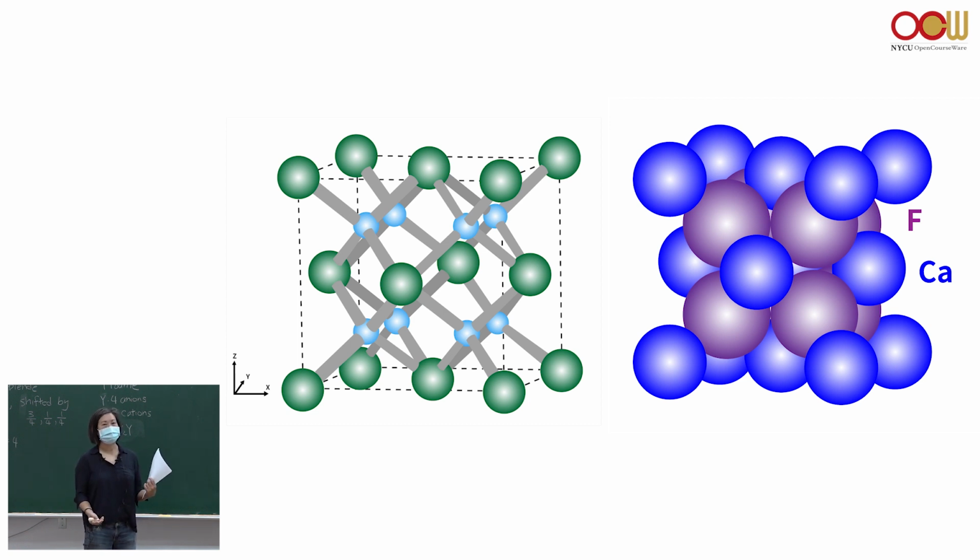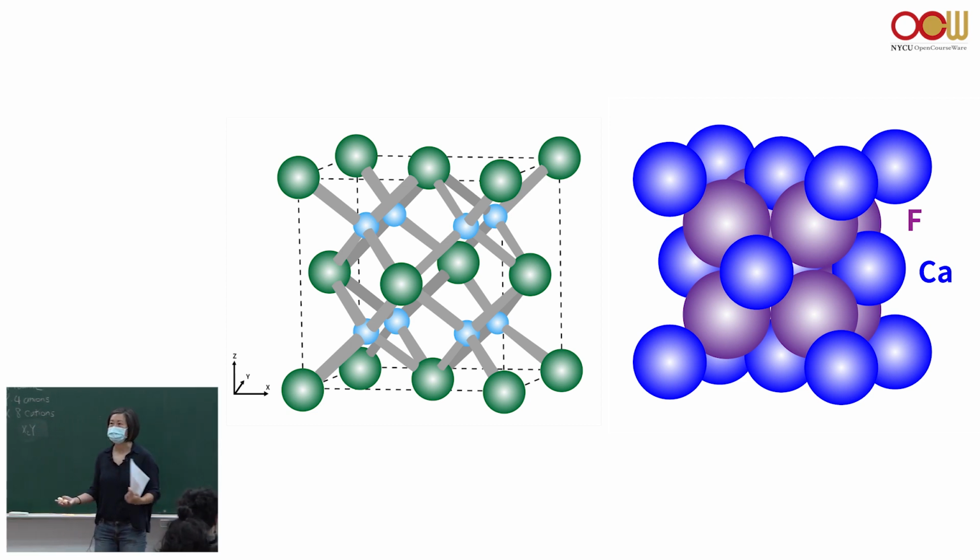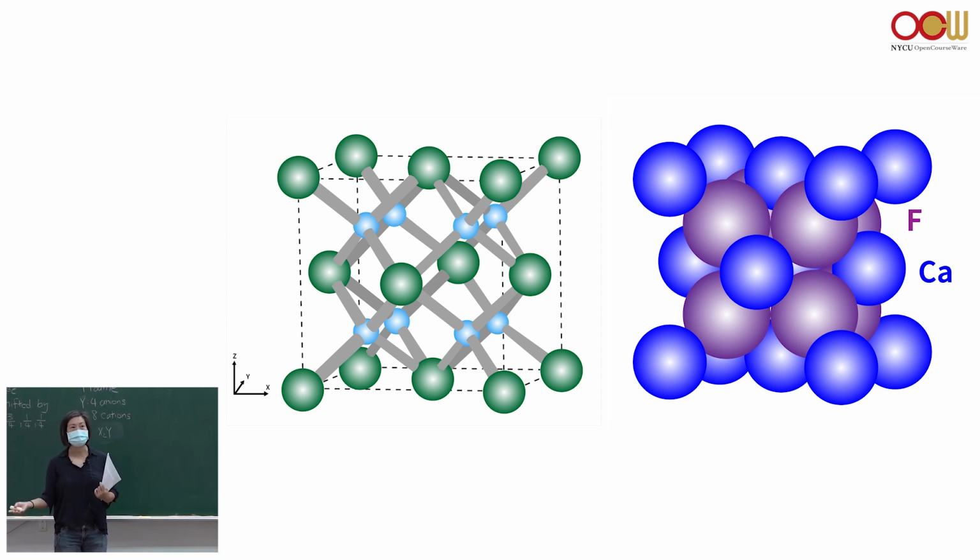And you're not going to need to memorize anything like that. If you eventually end up working with ceramics in industry, those are all things that you could look up in a handbook or online. And so the main idea here is to understand that ceramic materials are also crystalline. They have crystal structures, and that these crystal structures have to balance between the cation and the anion. That the size difference between the cation and anion is important, especially if it's ionically bonded, right? And that the structures can become very, very complicated.